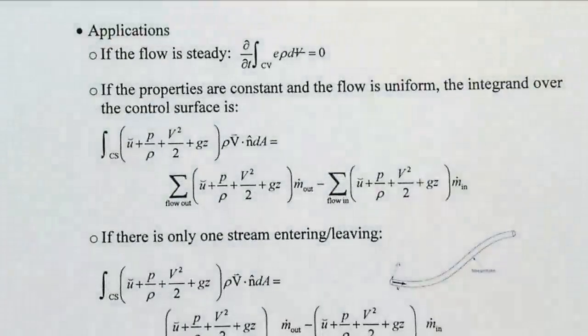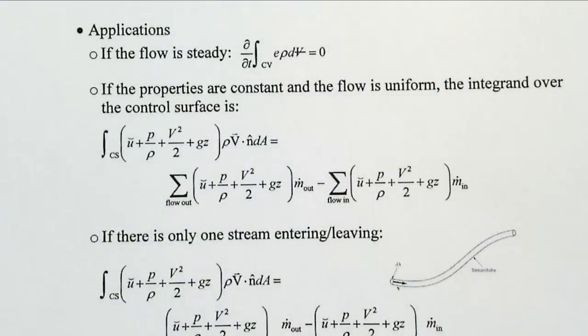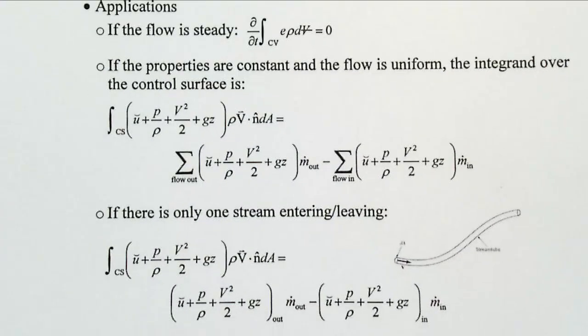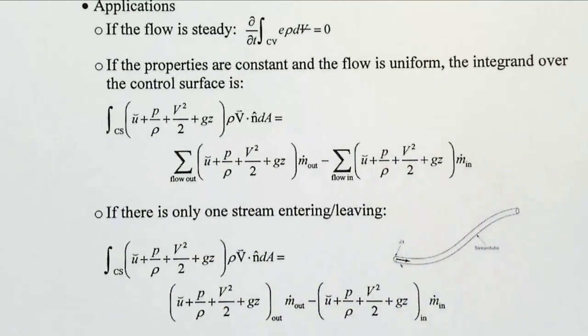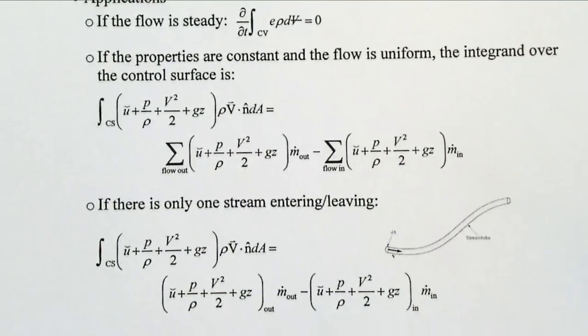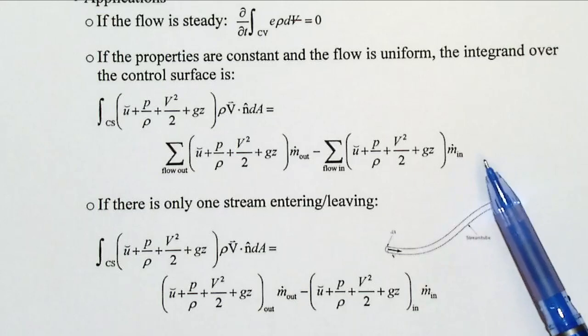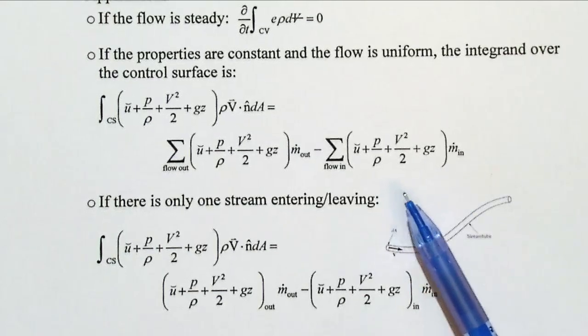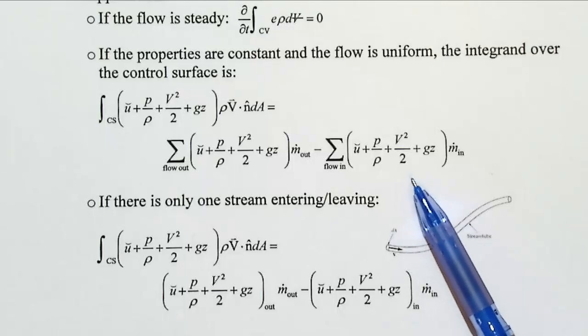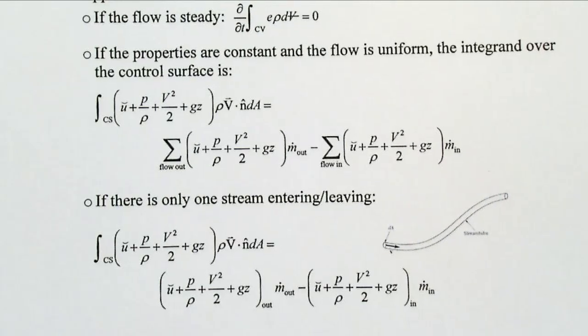If not, the question will tell you that that much of the energy is going to pass as heat to the control volume or out of the control volume. Then you can say that the summation of these two should be equal to the left hand side that you had in the conservation of energy, like Q dot net, and if you have a shaft you can calculate the W dot net. But these are all based on assumptions, okay? You simplify the right hand side, but the left hand side by itself is easy to calculate.